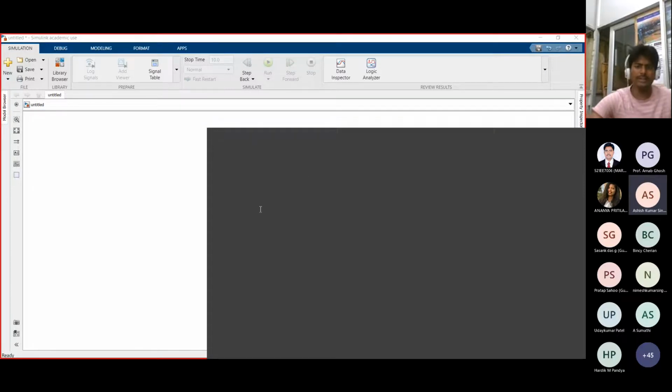In any system, there is one physical system and another one is the control level system. So here at the physical level, the DC voltage source, universal bridge, filter and load all come under the physical system. And for the control part, here I'm using ABC to DQ control. From the VI measurement, I can get the VABC. So by using ABC to DQ, I can get the Vd, Vq, and similarly Id, Iq for current.